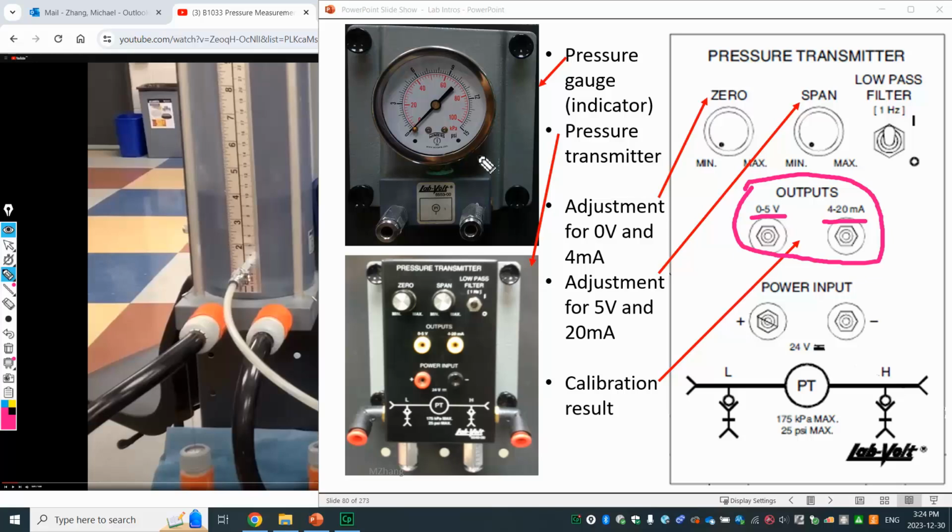On the slide, you can see that normally with pressure, we can use a pressure gauge. But again, that's only an indicator, a visible signal. The operator can read from the needle here, but that has nothing to do with the control device. You can use this as a local device to monitor, but you cannot use this type of signal for electrical control. So that's why we need to get the signal out from here, right?